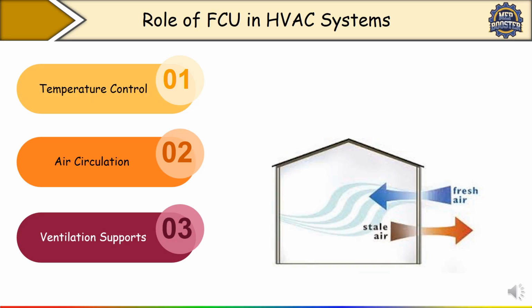temperature control. So, let's say for example, a small classroom. In a small classroom, generally an FCU connected to an external fresh air duct provides ventilation by bringing in fresh outdoor air while maintaining the room's temperature. So this setup helps improve air quality, preventing carbon dioxide buildup from students and improving the comfort environment. Okay, so this is the main purpose.